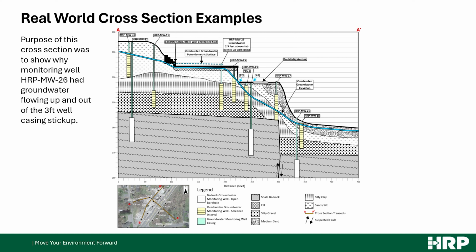We called these groundwater seeps, and we wanted to know if the groundwater was intercepting the surface or if this was caused by some other feature like a leaking water main or a pipe. What was causing these surface water expressions? In fact, in the actual air photo itself, if you zoom all the way in on Google Earth, you can actually see the sidewalk is wet from one of these seeps. So this is a persistent feature.